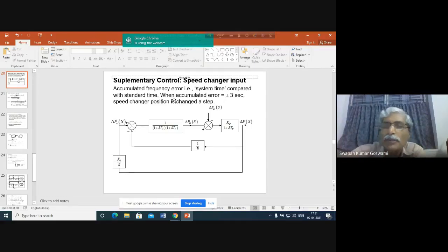So what is happening? Because he is drawing extra power, the system frequency is decreasing, because there is limited supply and more power is being drawn by the bulk consumer, which is supplying its load. In this way, the bulk consumer, without increasing its power generation capacity, exploits the system by taking power from it. He is paying for that power, but he is drawing power at a time when the system is already heavily loaded. He is drawing more power, which means frequency is decreasing.